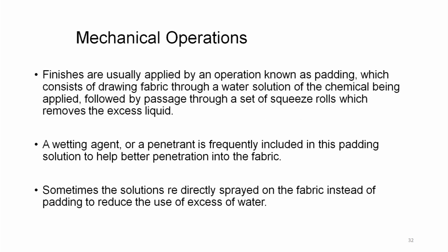Mechanical operation. Finishes are usually applied by an operation known as padding, which consists of drawing fabric through a water solution of the chemical being applied, followed by passage through a set of squeezer rolls which remove the excess liquid. A wetting agent or a penetrant is frequently included in this padding solution to help better penetration of the fabric.